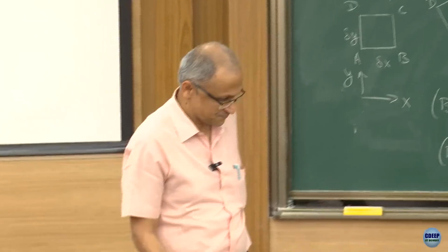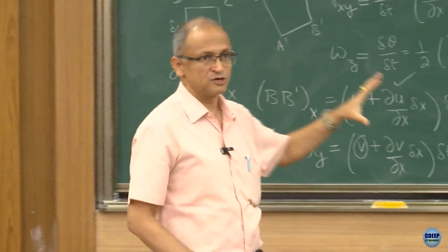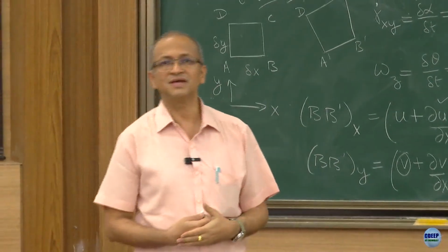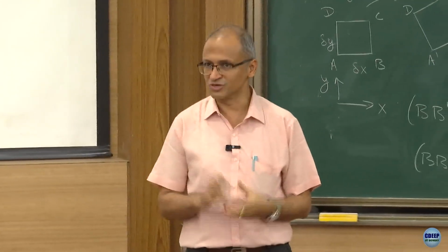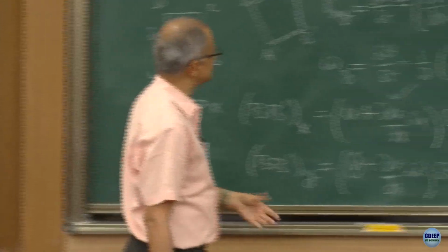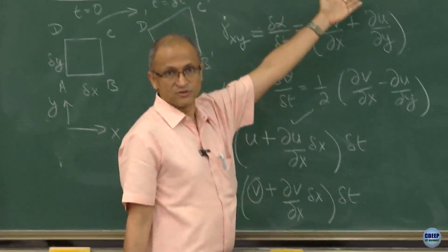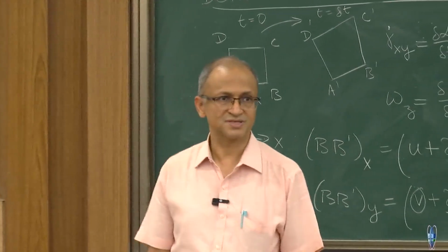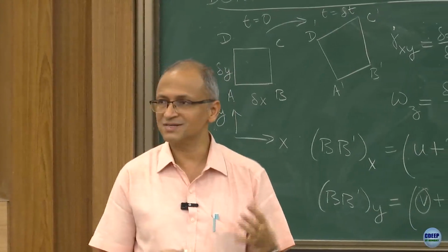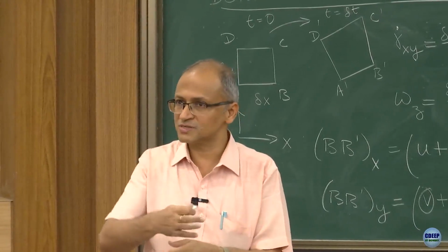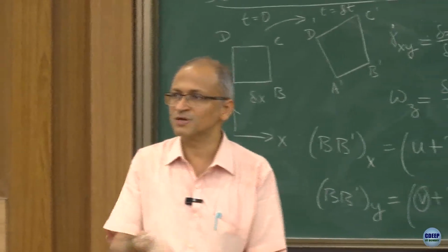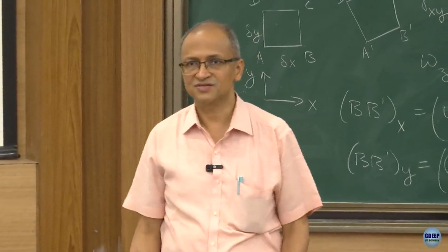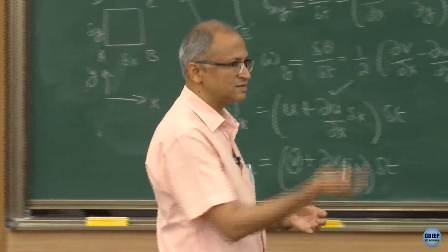Okay, so this idea of deformation of fluid element is very important, because it brings out the idea of rotation of fluid element, which we will call vorticity when we go to the vorticity chapter. This is actually vorticity, and the other one is pure deformation, and this deformation will get connected to your stresses. So we'll see that because of this deformation there is a stress, and that is going to be viscous stress if I multiply this deformation by mu. So that will become my stresses that the fluid will undergo, and then that will enter into the momentum equation.